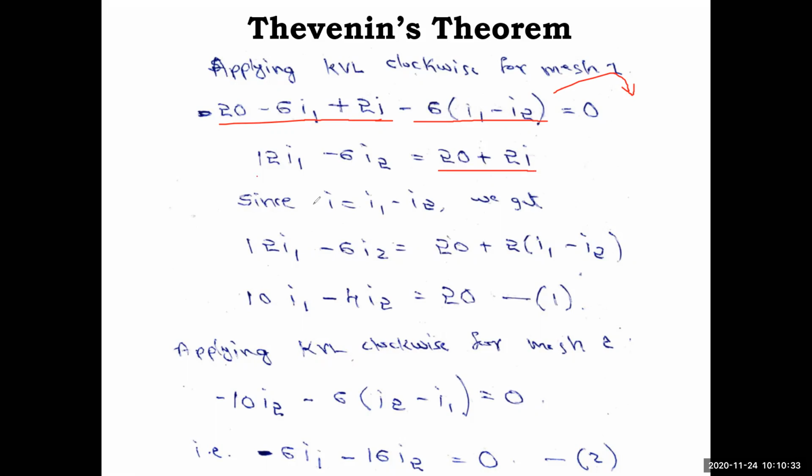So now we have to substitute for I. What is I? It is the current across the 6 ohm resistor. Since the circuit is closed, it is not straight away the current I; it is now the I1 minus I2 current. So that's why we have to substitute there. So this is the same, 12 I1 minus 6 I2, and here I will substitute 2 (I1 minus I2),